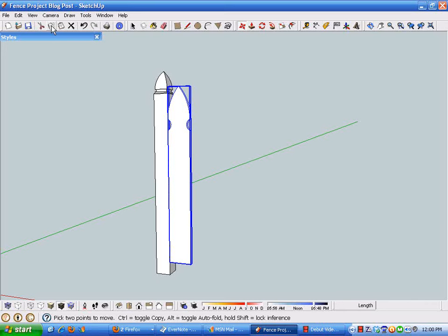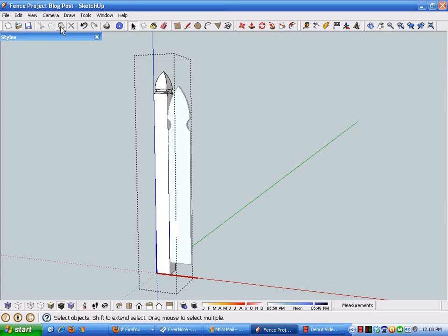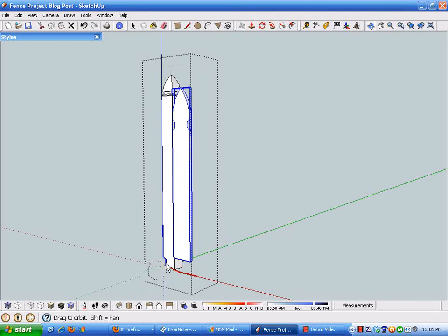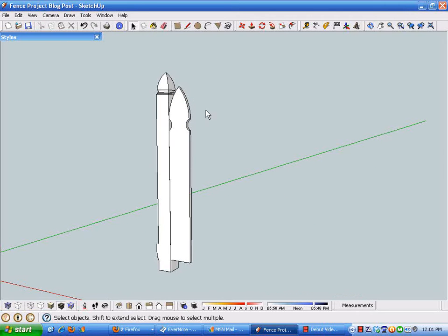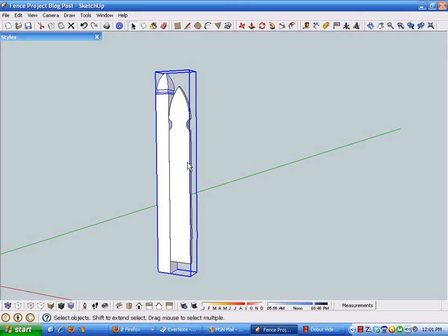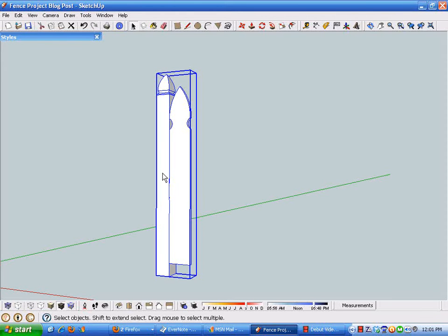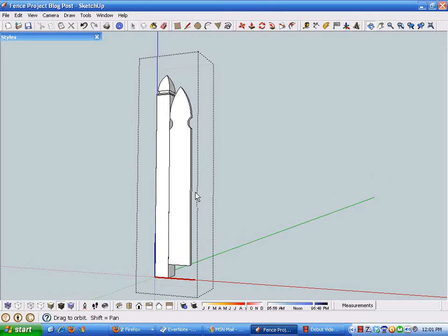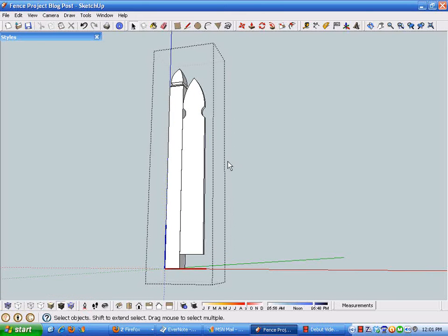component, I am going to copy that picket and then enter into the fence post component edit mode and paste the picket into that. So now what you see here is actually 3 components: a fence post with a picket attached to it, and then a separate picket component. So we're just going to delete that picket component on its own. The only one that's left is attached to the post. So jump into the edit mode of that post, which still contains a picket.